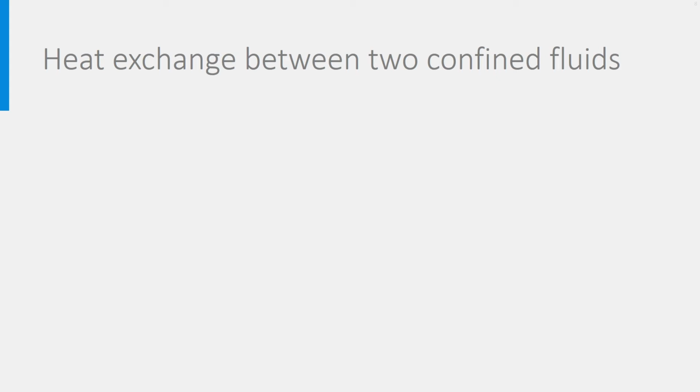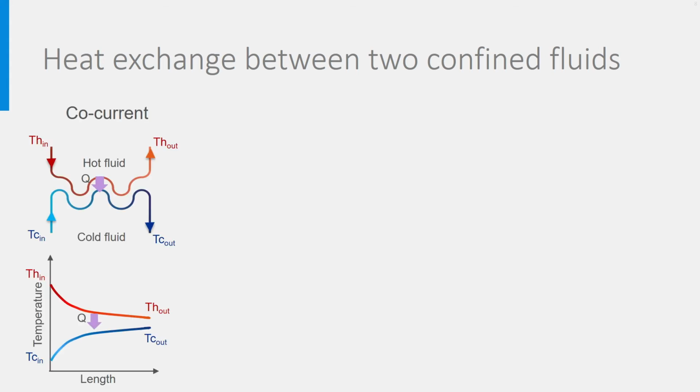Up to now, we have looked at heat exchangers immersed in a medium at constant temperature. But most of the time, the design is such that the heat transfer takes place between two fluids in movement in two different pipes. It may be water-water or air-air or air-water or refrigerant-water or refrigerant-air, etc. In short, there are two pipes being in thermal contact and exchanging heat together. Like here in parallel flow, also called co-current heat exchangers. The heat exchange is from the hot fluid to the cold one. The hot fluid is then cooled down while the cold fluid is heated up.